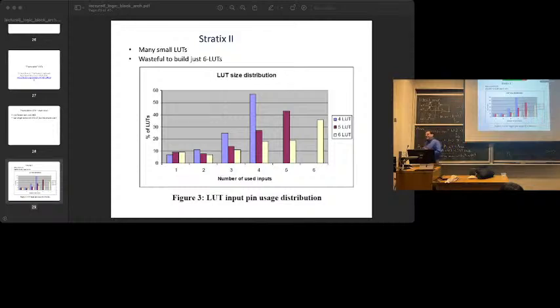When you're using some of the inputs, it's painful. Like, it works, but you basically built a LUT that is exponentially bigger, right? Like the 6 LUT took you twice the area of the 5 LUT. So if you're using this 6 LUT as a 5 LUT, the LUT itself is twice as big as it needed to be. And it has 1 extra routing port, which I also paid for. So this is kind of a waste.